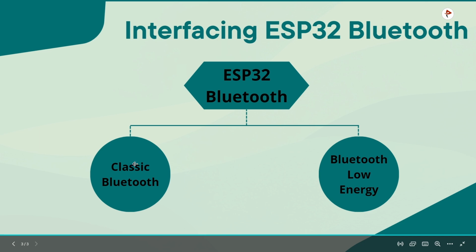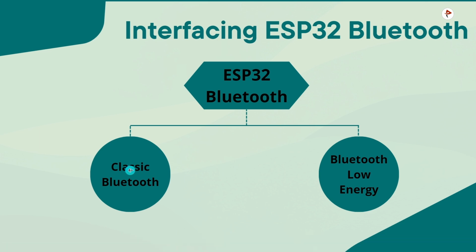So this Classic Bluetooth, also known as Bluetooth base rate or enhanced data rate, is the original point-to-point network topology designed for one-to-one wireless communication between master and slave. Even though multiple slave devices can be connected to a single master, only one slave can be actively communicating with the master. Our Bluetooth keyboards and mouse work with classic Bluetooth technology. Another simple example is file transferring between two devices like two mobile phones or a laptop and a mobile phone over Bluetooth, which is based on classic Bluetooth functionality.